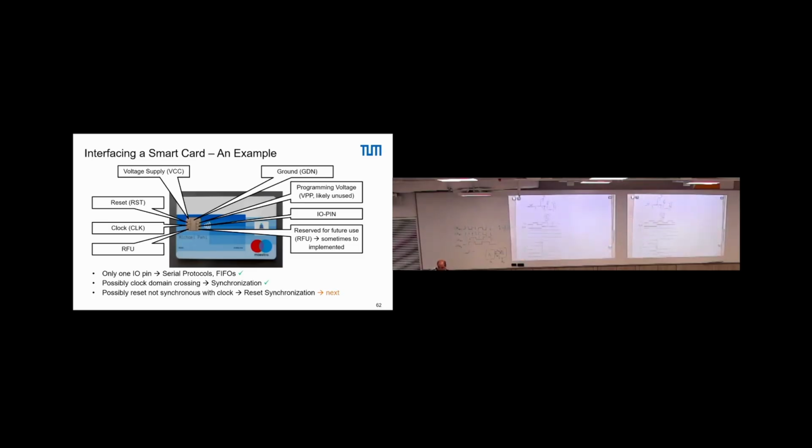Okay. Now, since we evaluate with our clock, so we evaluate effectively with this clock edge here. At that point, this one here is already 1, but the other two are 0, right? So the lower two signals here, for the point in time where the clock edge occurs, are both 0. That means our flip-flop is still in reset. Our value here stays at 0 and only goes up for the next rising edge later in time.